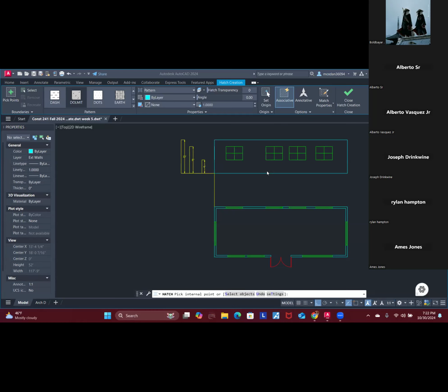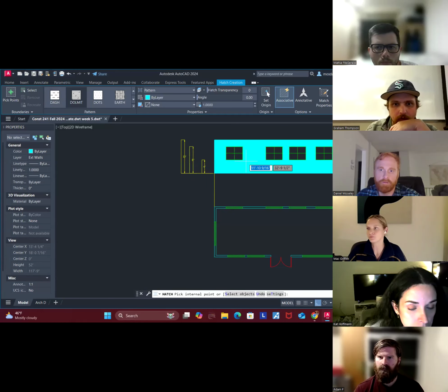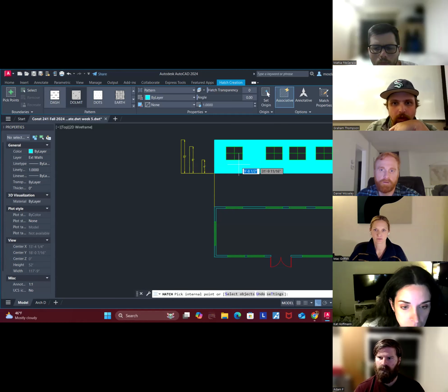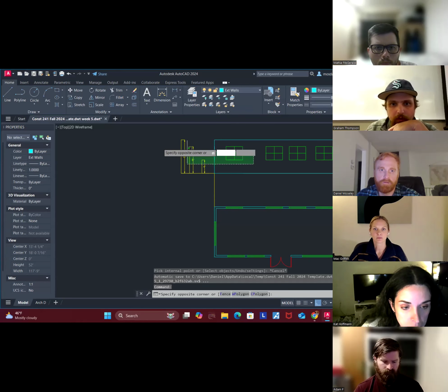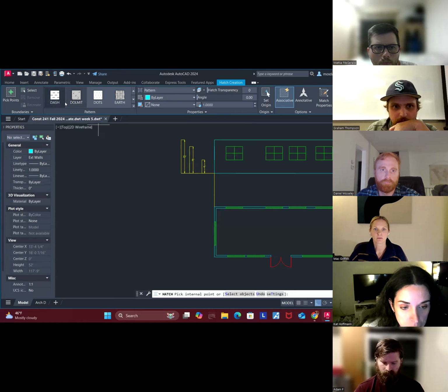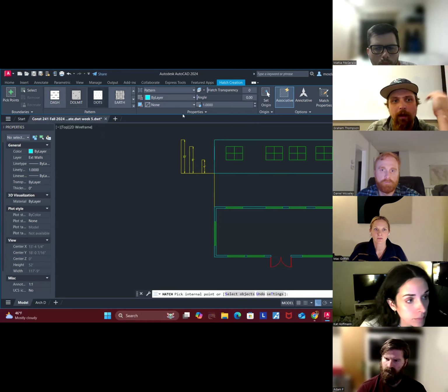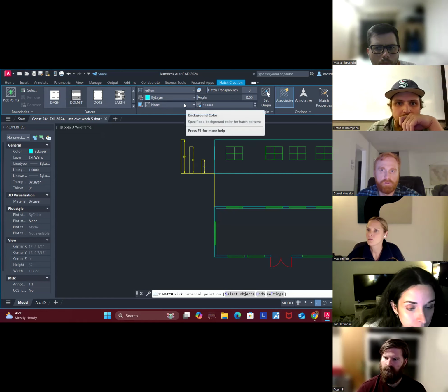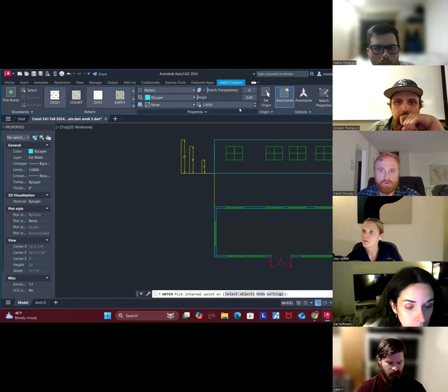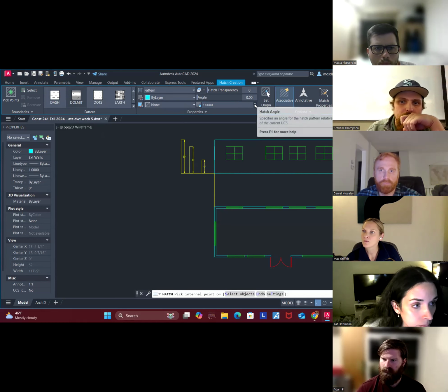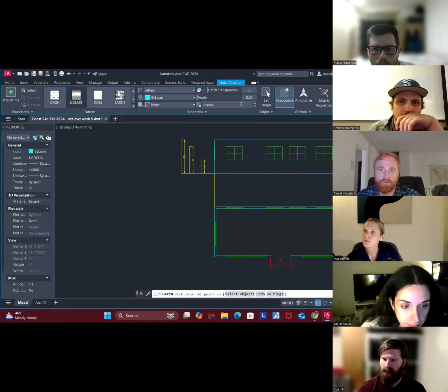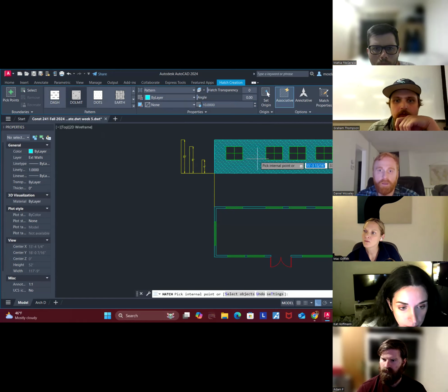See, if I click on it, it's just like that. Okay, perfect. Now go up to that scale. Click on it. Go to hatch. Say I want to use this one. You can do this before or after, but where it says 1.0000 to the right, change that to 10. You can type in 10. It might be faster. Now try to drop that hatch on the wall. Oh yeah, way better.